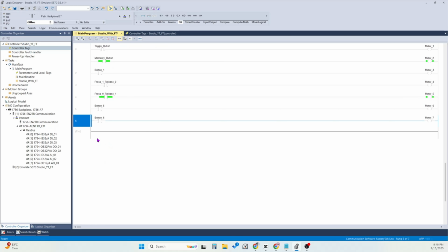So in this video I will show you how to build a multi-state button to control different modes, a multi-state indicator to display those modes, and a rectangle with multiple color animation for clear visual feedback. This is exactly how real SCADA systems are built in food, beverage and oil and gas plants. So let's create a tag in Studio 5000.